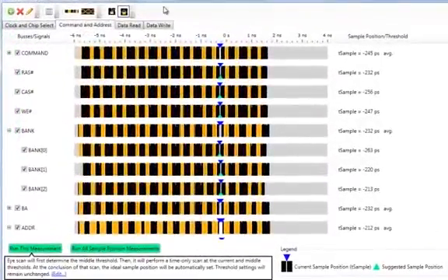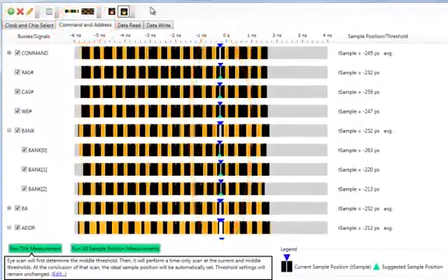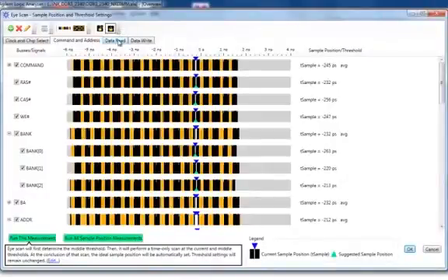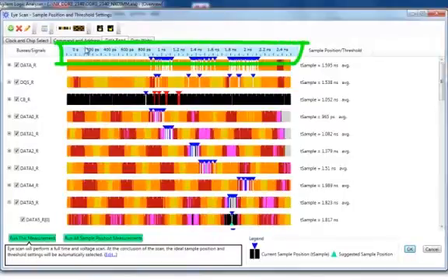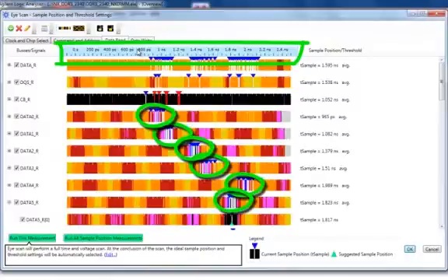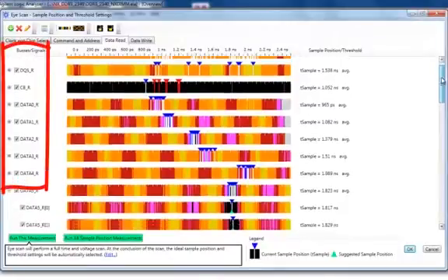You'll be able to use the sample positions DDR Setup Assistant chooses for clock, chip select, command, and address. On the really high data rates, it's a good idea to go in and check the eyes for the data read and data write. Here on the data reads, I've narrowed the span to be just the area 0 to plus 2.5 nanoseconds, where we see the data bytes occurring. This lets us see the eyes better when they are so small at these high data rates.